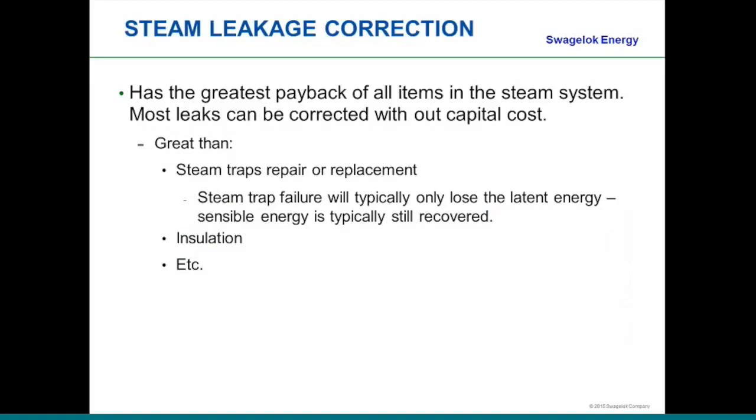People always say, go out there, correct the steam trap failures, it'll save you all this money. Steam leakage is far, far higher payback than steam traps, insulation, et cetera. So if you're looking to optimize the steam system, steam leakage is the number one or maybe even number two area that you want to take a look at.